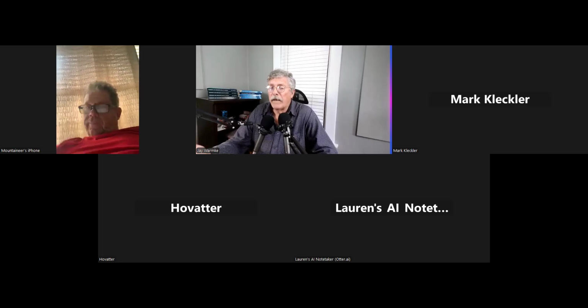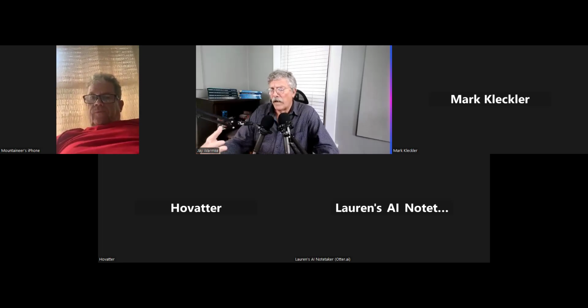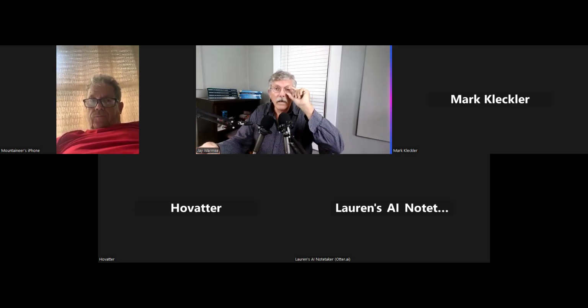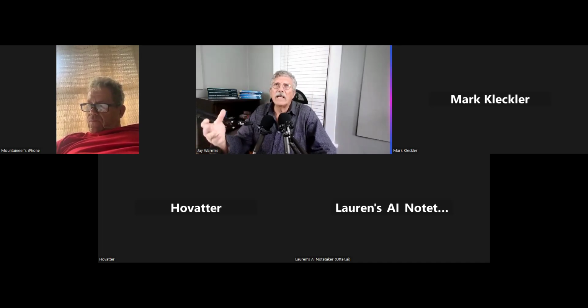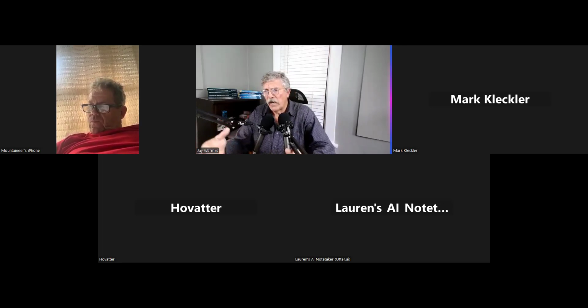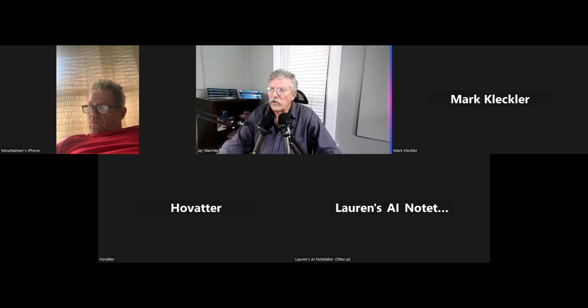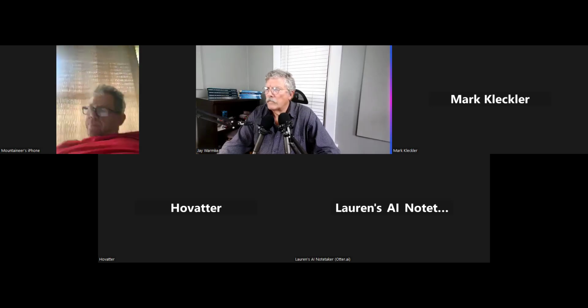One of the things that I do recommend when you sit down: there are a couple of equations that you need to have memorized or at least know how to use. The power equation, watts equals amps times volts, pretty straightforward. Ohm's law, which is volts equals amps times resistance, or VER. And then there's the voltage drop equation. And voltage drop is really just Ohm's law adjusted for distance. In fact, let me show you the whiteboard here.